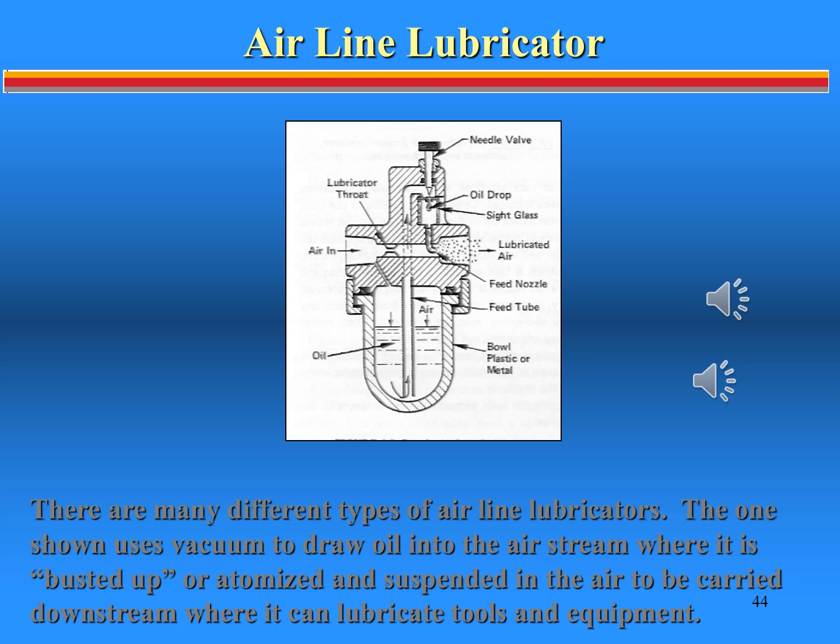The oil travels up the tube from the bowl, through the transparent housing, past the flow adjusting screw, and then drips back down into the airstream as long as the air is flowing through the lubricator. Depending on the style of the venturi and the speed of the air, the oil can be completely atomized or atomized to differing degrees. This atomized oil is carried out of the lubricator head in the compressed airstream and, providing the lubricator is placed close enough, downstream to the air tool or air component needing lubrication.